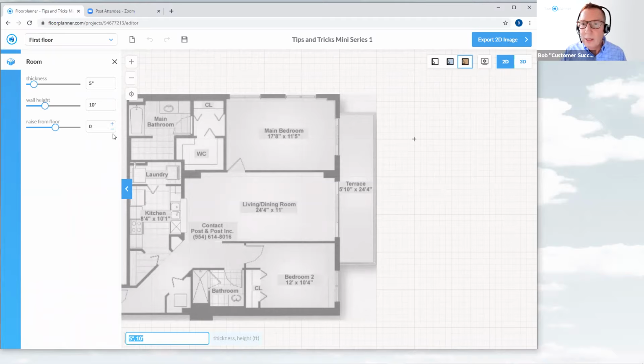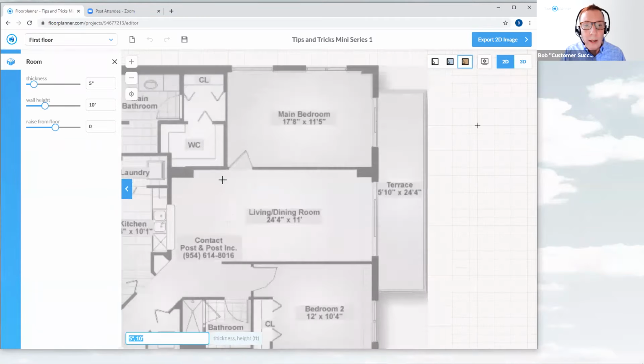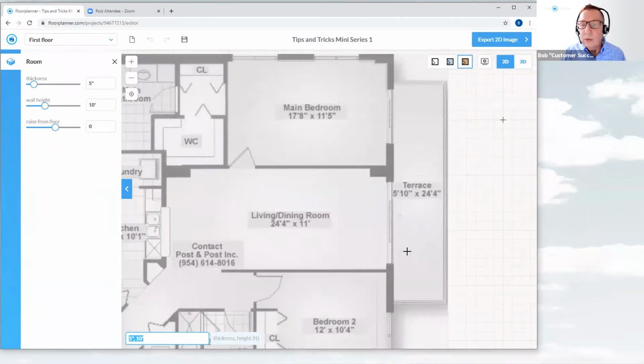Now, with these settings here, like we did before, how we just drew out a box, well, there's the crosshair, and there's the circle inside of it, and I can go ahead and trace a room, but I'm going to trace a square room right now just to keep this simple. We can always modify it later and add walls, change walls. But when we're drafting, like I mentioned before, we're drafting from the midpoint of the wall. Very, very important that it's in the middle.